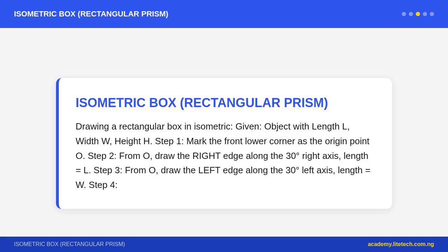Cylinder in isometric. Step 1. Draw the top ellipse, circle face, using the 4-center method. Step 2. Drop vertical edges, parallel to the vertical axis, of length equal to the height of the cylinder. Step 3. Draw the bottom ellipse, using the same method, displaced downward by the height.